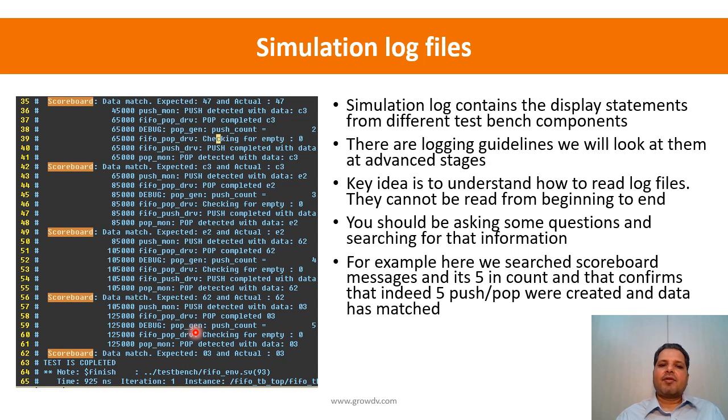You should identify that localization information, which you also call triaging, using the log file. So using the log files, you have to do 2 things. One, whether the issue is a test bench issue or a DUT issue, right? You should try to figure that out to the extent possible.